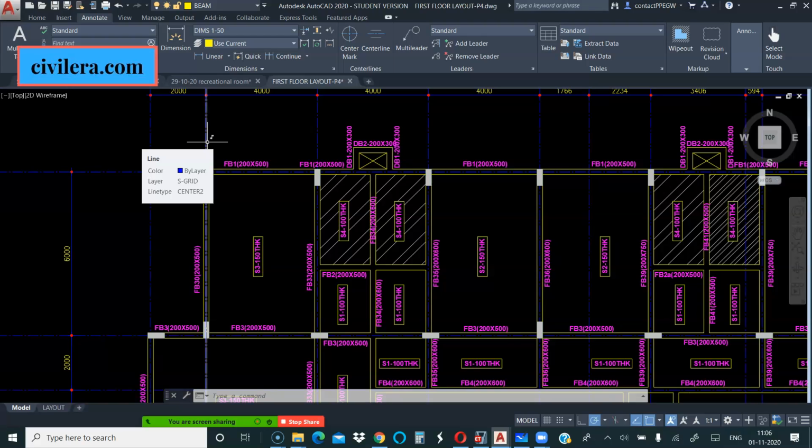It will come to you with experience, but as a rough rule I'm telling you, not more than say 6 to 7 meters and not too less. Now if you ask me, can it not be 8 meters, there is no hard and fast rule, as I said. If your span is 8 meter, then your beam dimension also will have to be slightly more based on the requirement. Your column moments also might be more. So if there is a situation in one place that you need 8 meters and you have no other solution, then yes, you go for 8 meter. It's not a hard and fast rule, as I said.